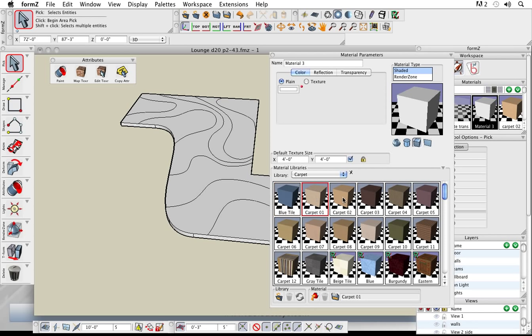If you see one that you like, just simply take it and drag and drop it onto your material, so that all those predefined parameters are now assigned to your material up here. So this is a lot easier than what it was in the previous version, in which you had to go into a couple dialogues, you had to find the material, apply it, and come back to the material server style. So here it's one stop, boom, it's right there in one single palette.